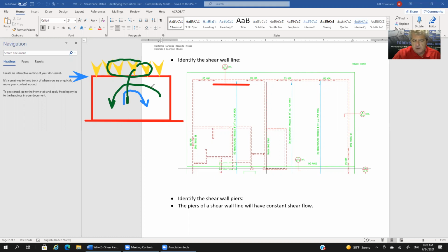So the bigger the piers, the less likely that they are to be susceptible to overturning. So by inspection, we're not going to evaluate this one. I think almost by extension, I would say the same thing about this one, right? Now it looks to me like potentially what we're looking at is possibly this pier and possibly this pier as being the more critical ones. Okay, so now let's indeed look at this pier here.